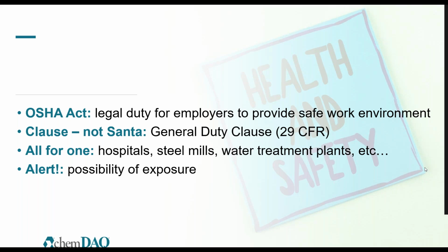Right. So again, we're working with something that doesn't have an IDLH. They've thrown out an IDLH value in the past, roughly 5 years ago, and nobody could really agree on it. So again, you're dealing with things that are changing, people who disagree on what the level should be, and you're basing on 3 different levels: the instantaneous, a 15-minute STEL or short-term exposure limit, and then an 8-hour permissible exposure limit.